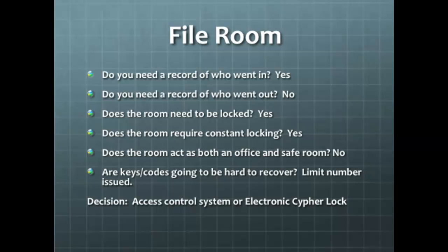So I would go with electronic access control on that, for sure, card reader, but only on one side, which means if there's a reader on one side, you have to have something to let the door unlock on the other. That's a REX. And then we talked about maglock or electric strike. Either one's acceptable. I used a strike in there because it just seemed like an easier way to go for me. I'm not even sure why I would choose that.